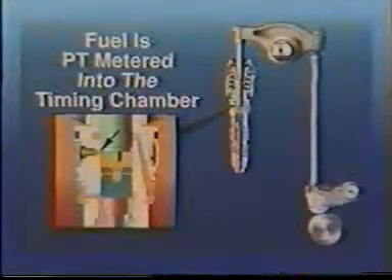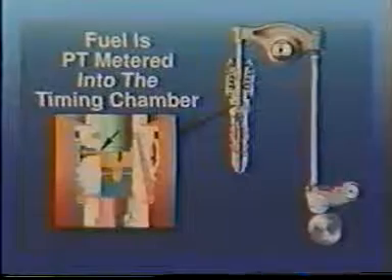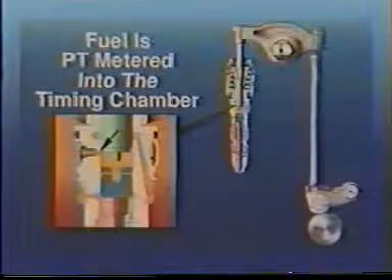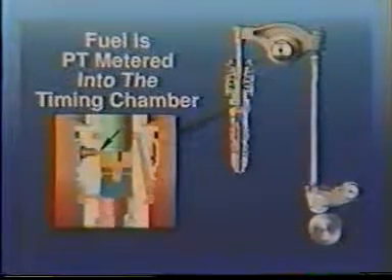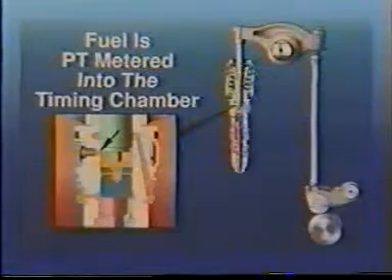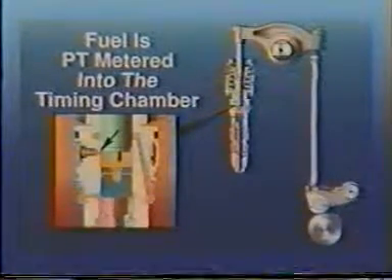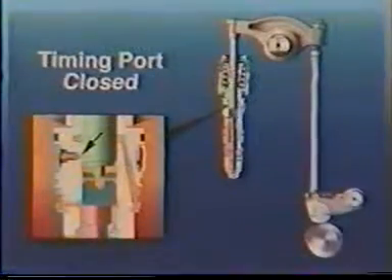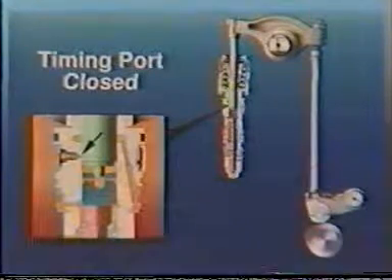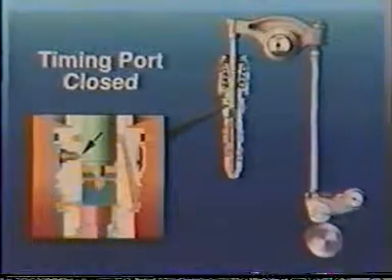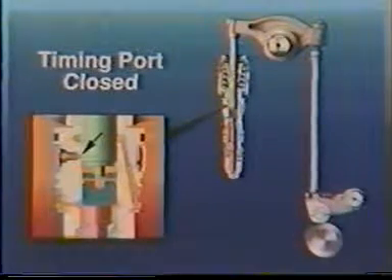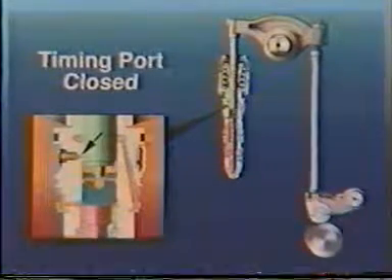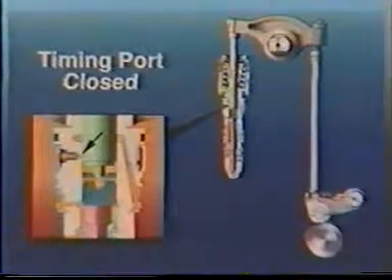The cam follower continues to roll toward the inner base circle, allowing the timing and upper plungers to continue moving upward. When the upper plunger retracts far enough, it uncovers the timing feed port, and fuel is also PT metered through an orifice into the timing chamber. As the cam follower starts up the injection ramp of the camshaft, the upper plunger will move down and close the timing feed port to end timing metering. The fuel that is metered into the timing chamber is now trapped between the upper plunger and the timing plunger.